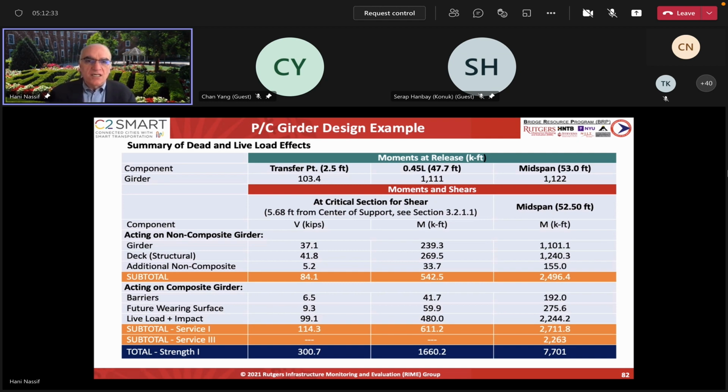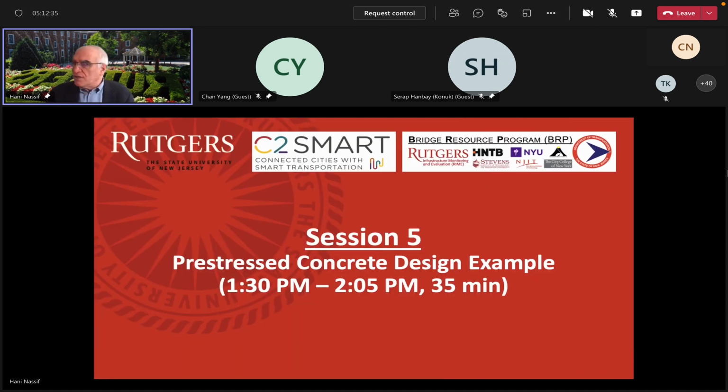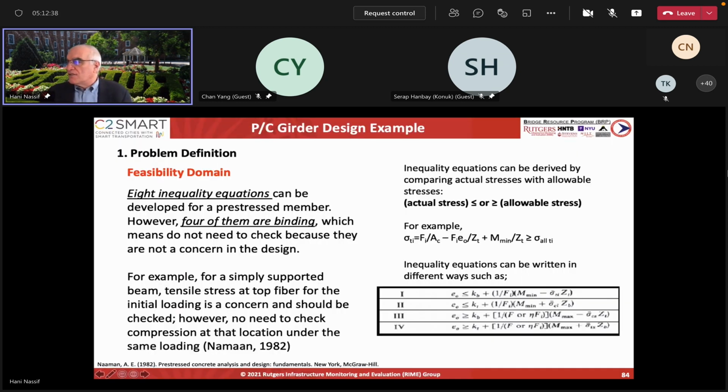So what people have done here is use equations, what we call the stress equality equation, meaning you could find the stress at any point on top of the girder or bottom of the girder based on this equation, okay? It has the pure compression from the pre-stressing applied axial force divided by the area. That's the total compression that you're applying. Then you have the stress from the pre-stressing itself: the eccentricity times the force gives you the moment that the pre-stressing applies, opposing the dead load, okay?